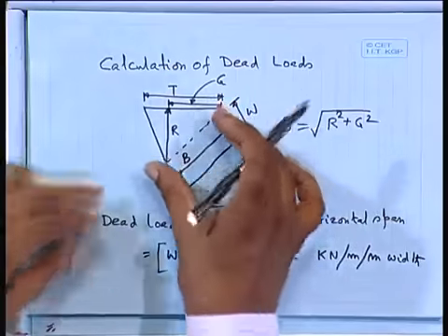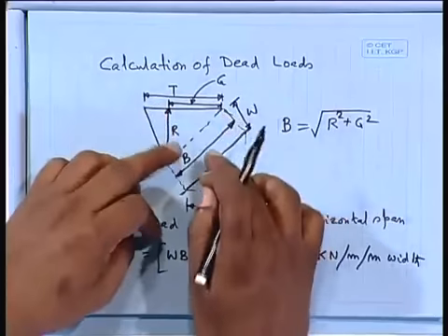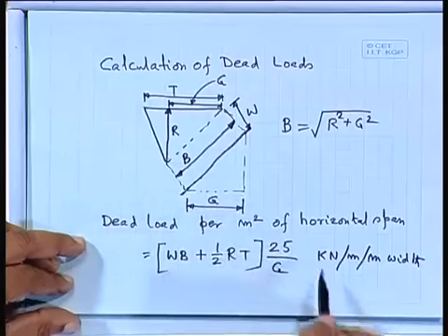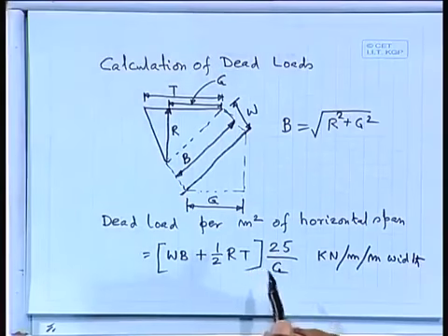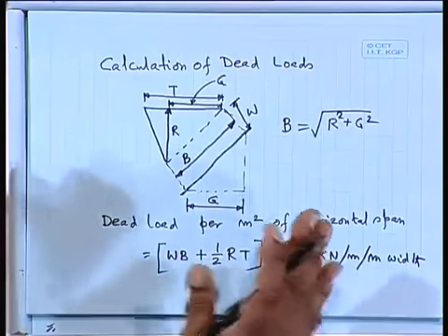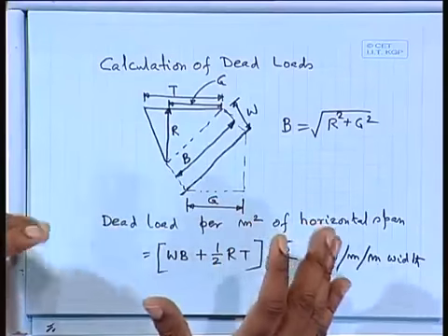So, that means if you project it, it will go up. So, you will get something that in 3 dimension you will get this is the unit one, and so I shall get per meter width, and this is the weight I can find out, that is the dead load, you can get it. So, in your whole design, so far as the staircase is concerned, if I can calculate the dead load, now we can consider it as a, say, slab or a beam.